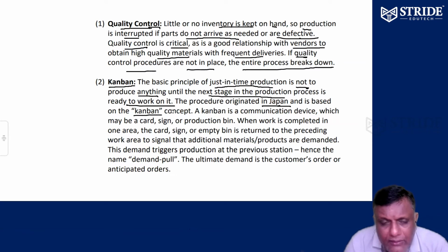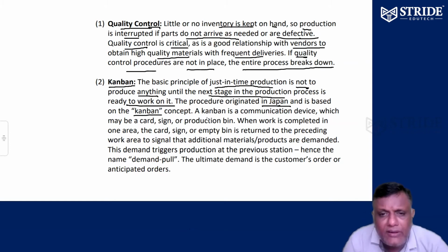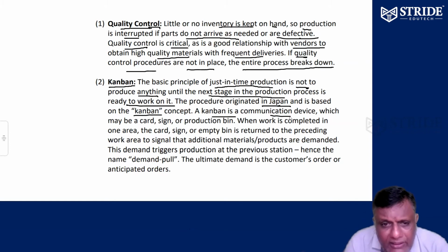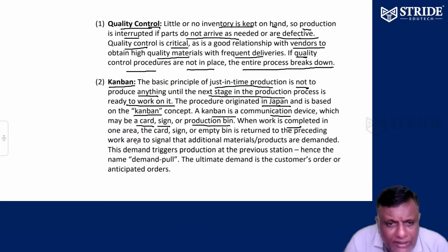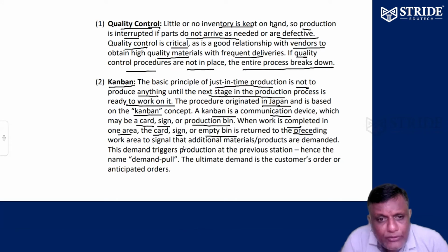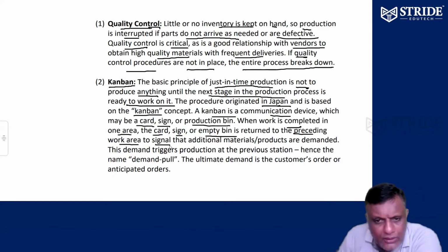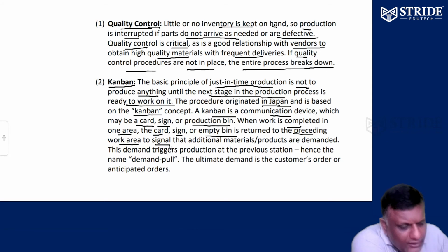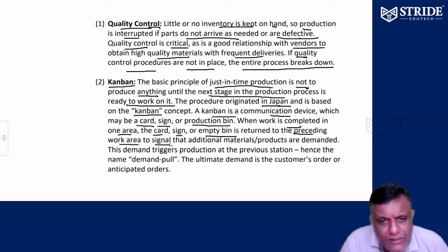The Kanban technique. If the next stage of production requires something, don't demand it beforehand. Kanban is a communication device, which may be a card, a sign, or a production bin. When work is completed in one area, the card, sign, or empty bin is sent to the preceding work area, which means, sorry, empty bin, I need material. So materials are used, and again an empty bin is sent. Again materials come in, are used, and again an empty bin is sent.